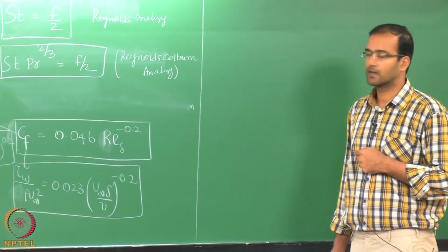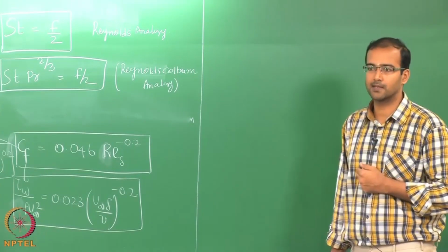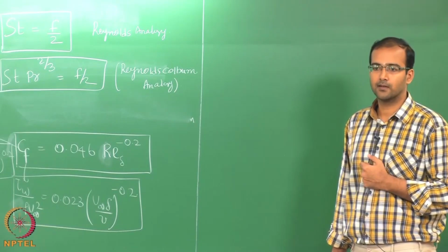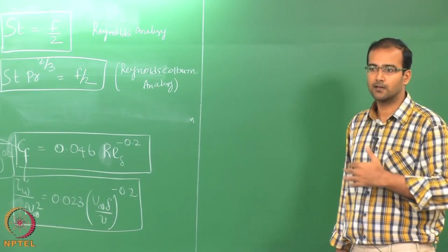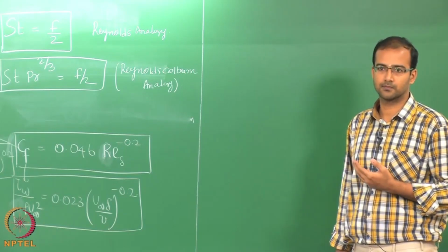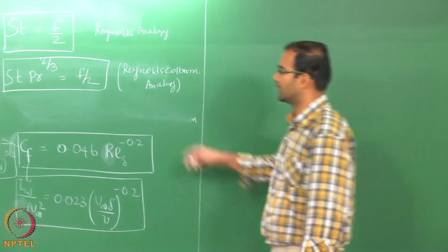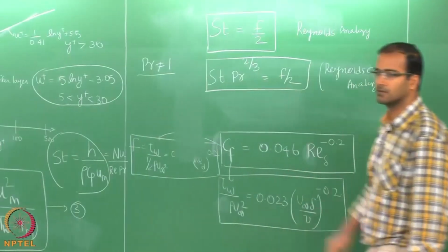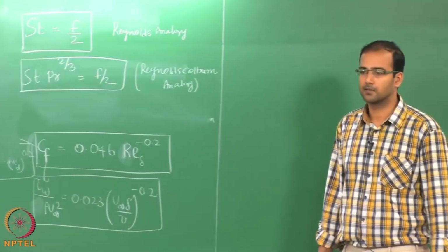We cannot claim that we can predict the Nusselt number, okay, Nusselt number is a quantity at the wall, without accounting for the laminar diffusion. So, therefore, later on Colburn adjusted this for values of molecular Prandtl number.